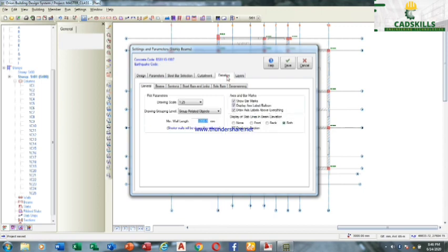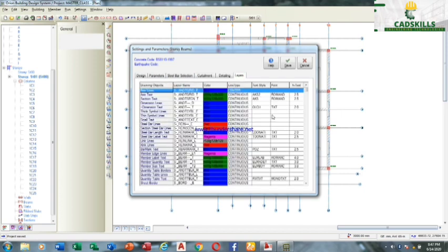Okay, come to your detailing. How do you want your detailing to be? He said it should detail with 1:20 so that it can be bigger. He said that it should match related objects, group related objects. You can say minimum wall length 1002. You can increase it, depending on how you want it to be. You're the one now specifying. Axis, show bar marks. These are the things you want to bring out in your detailing. Show bar mark, display axis label, draw axis label, and so on. You say both ways, both front and back. Is that all right?